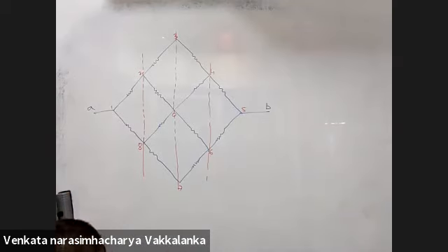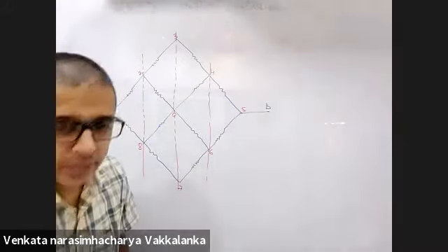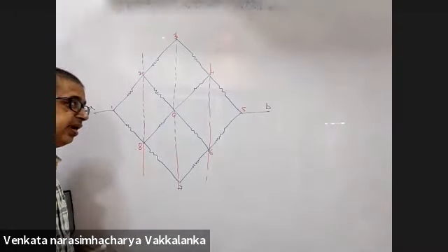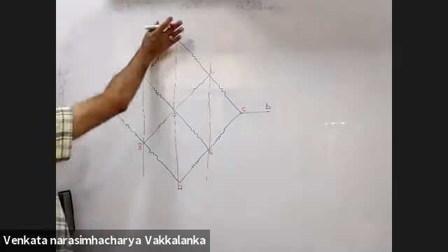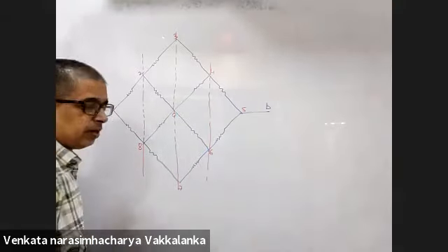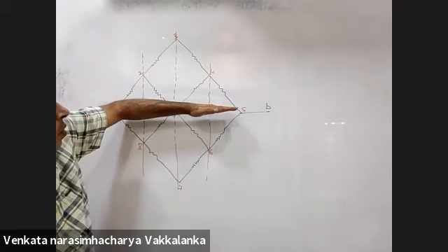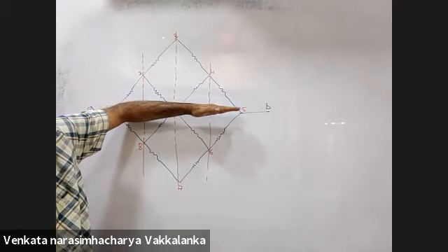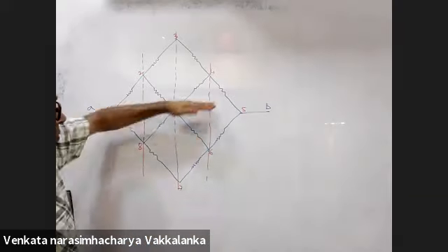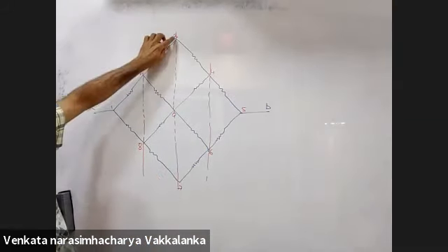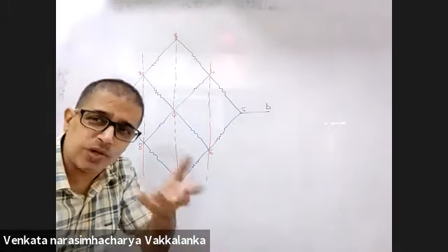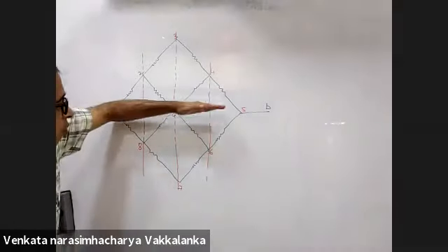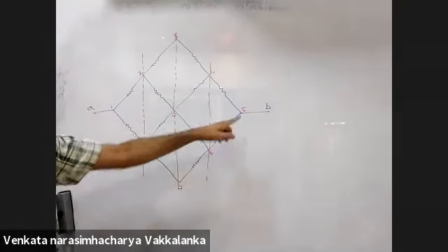Second rule of symmetry, a lesser used rule of symmetry. Fold the circuit along the line of the current. Why are you permitted to fold? Because when I fold, observe that 7 will come over 3, 8 will come over 2, and I am permitted to join them both because they are equipotential. Fold the circuit along the direction of current.